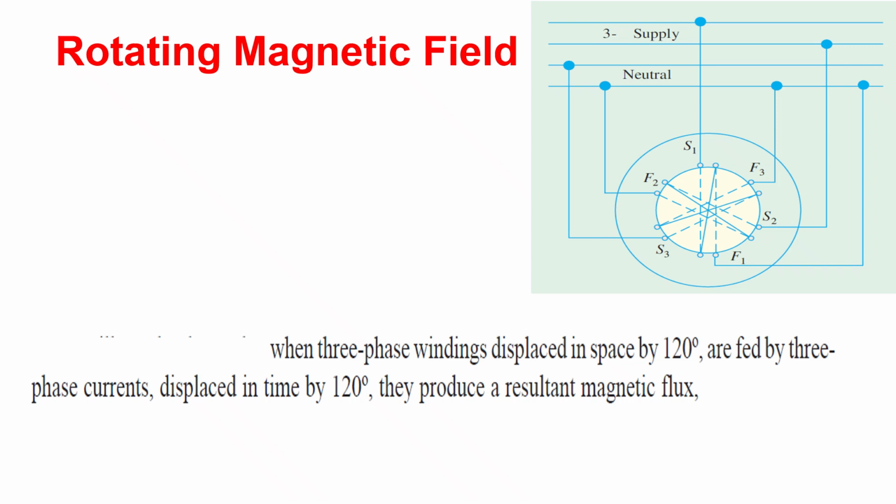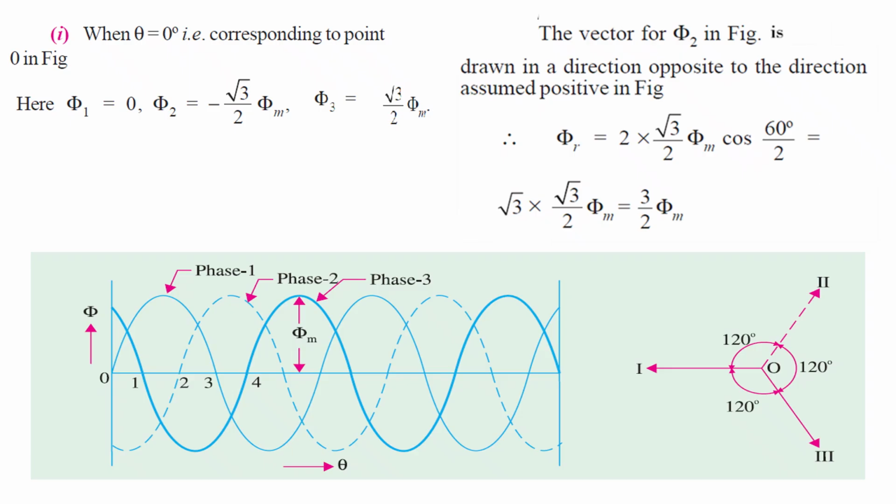Here the stator windings are energized by the three-phase supply, shown here, and each is phase shifted by 120 degrees. The red, green and blue colors show the currents excited 120 degrees apart.